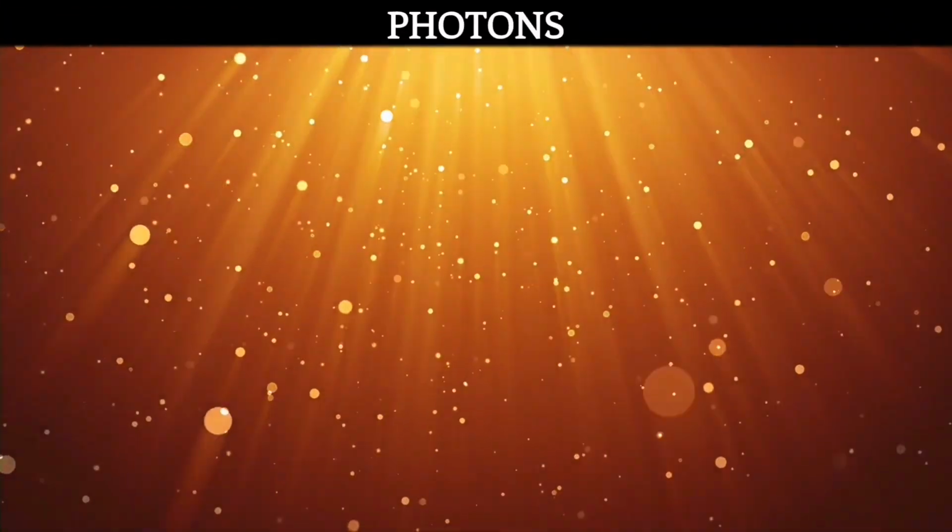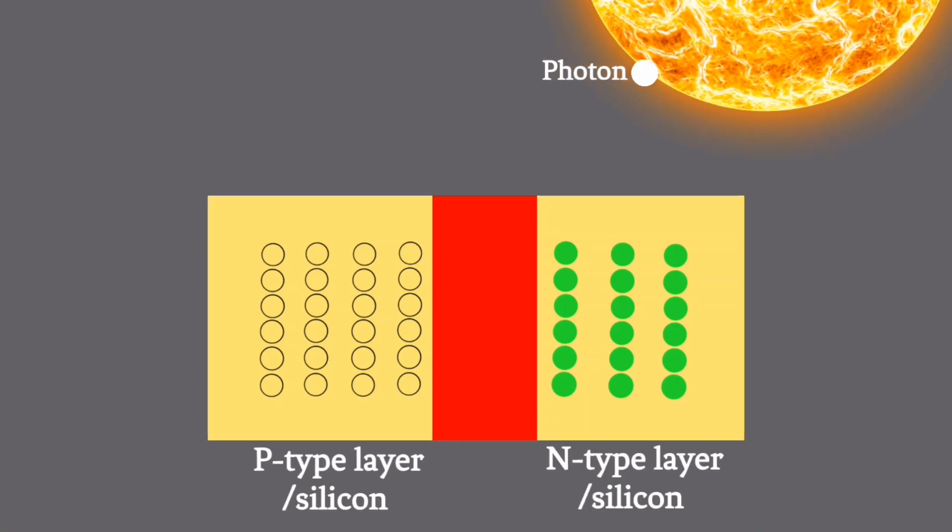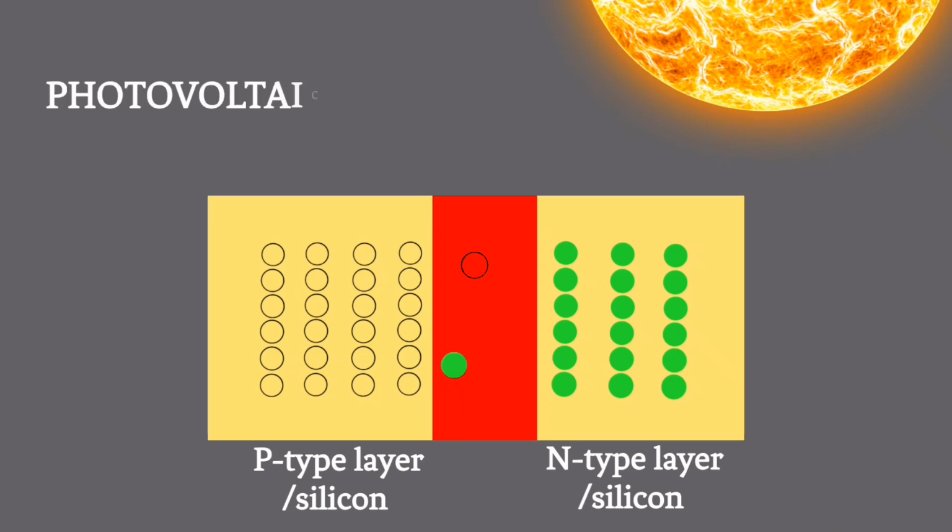Now, light is composed of numerous tiny particles called photons. When a single photon from the sunlight strikes the surface of the solar cell, it causes one of the bonded electrons to be released, leaving a hole behind. This process is known as the photovoltaic effect. The electric field at the depletion region acts as a one-way gate that directs the movement of electrons to the N-type layer and holes to the P-type layer.